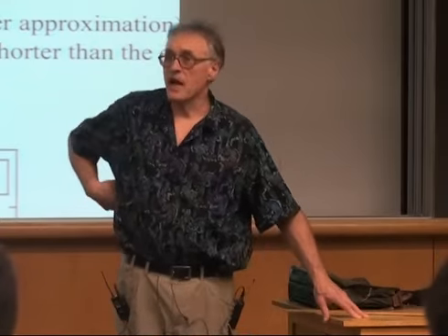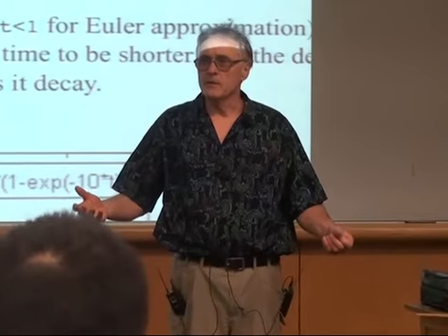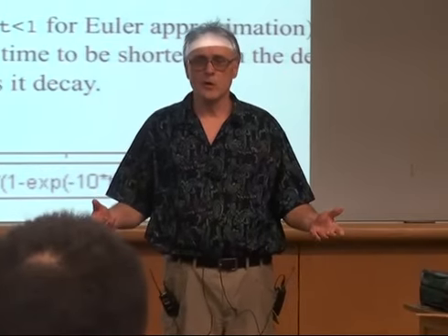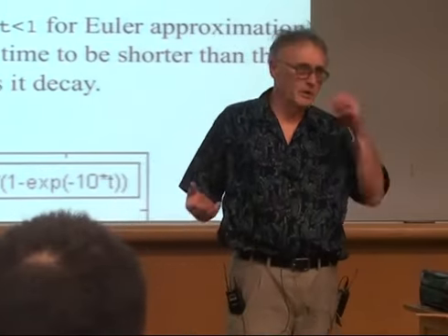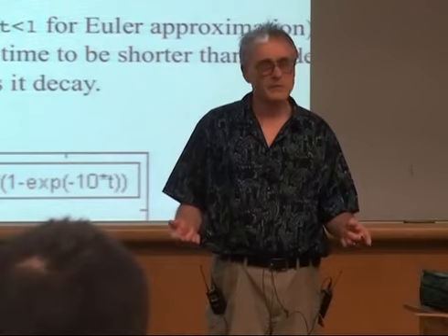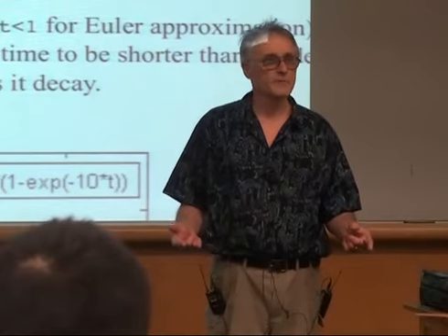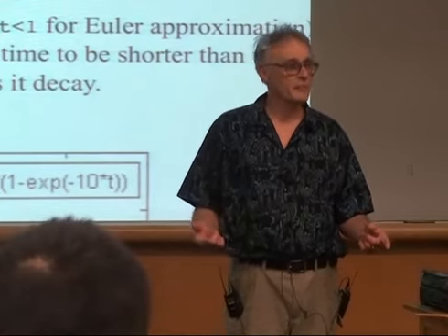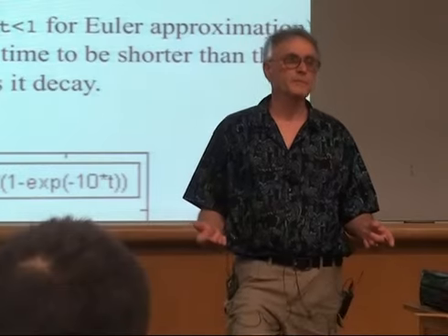It works for sine waves. Why shouldn't it work for an exponential? And what I said last time was, well, you wouldn't want to table drive this because you'd have to have lots of tables for different time constants. But that's not true. No more than it's true that you have to have a lot of sine wave tables for different frequencies. You just have to step through the table at a different rate.